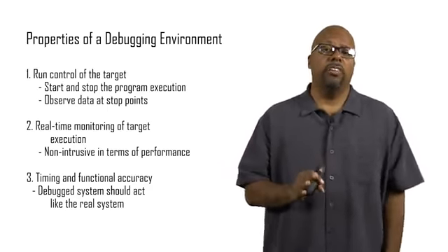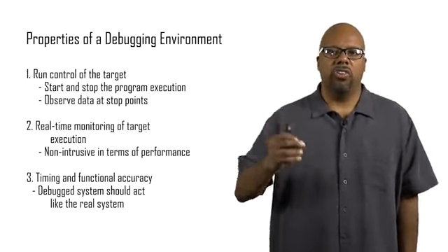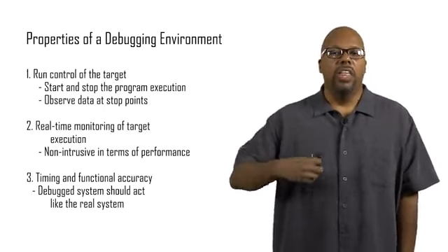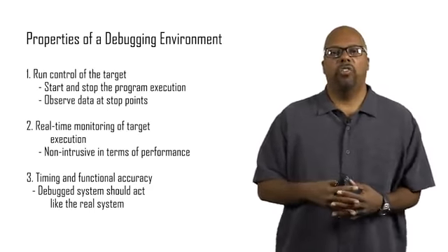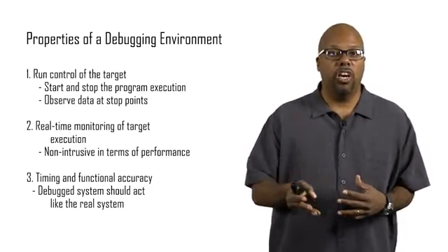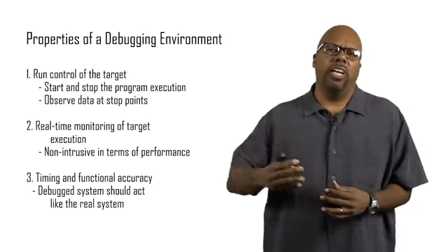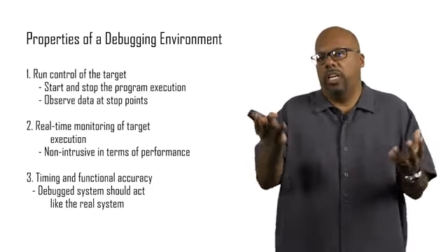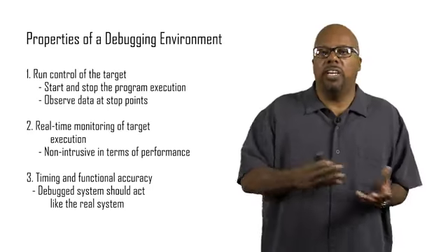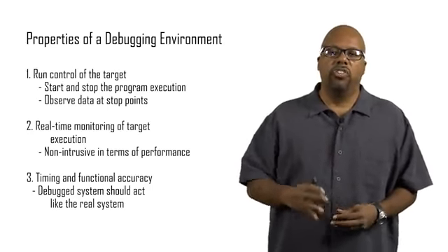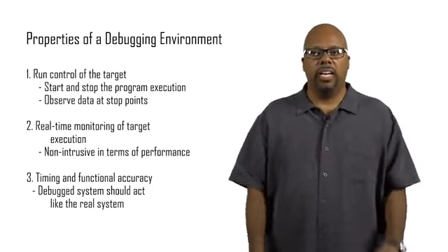Another thing about simulators is that they model most things, but there are certain things they can't accurately model. For instance, simulating an analog to digital converter is very hard. So sometimes simulators won't do that, and the results for the A to D conversion will be inaccurate. You might be doing an analog read, and then your analog read data will be incorrect because the simulator wasn't accurate enough. So you want accuracy in terms of timing and in terms of functionality, if you can get it.